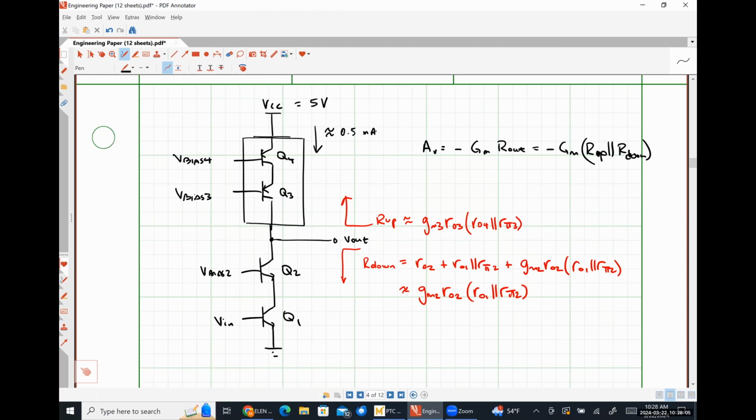All of that couldn't actually be on if we were able to actually drive half a milliamp through that 10 kilo ohm resistor. So putting physical resistors, we're never gonna actually be able to put a large enough resistor to it without forcing all of these transistors either very deep into saturation or worst case scenario.